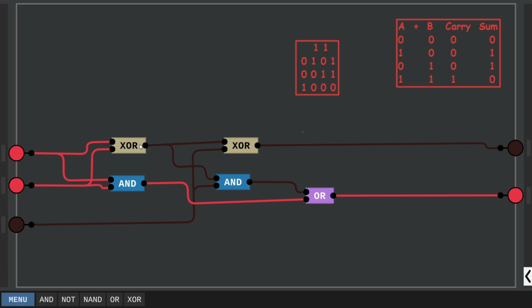So it will check if the carry bit is 1 and the XOR gate is 1 also, then it will produce another carry bit. In this scenario the sum bit is going to be 1, and if we add the extra carry bit which is this one, then the sum will be 0 and a carry bit will be moved to the next bit.